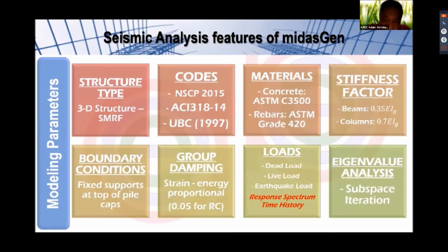Then the loads. Of course, we consider dead load, live load, and earthquake load. Now, just for the sake of doing this study, we consider the actual loading based on the present occupancy of this building. So the dead load and the live load are all defined using the actual occupancy of the building.